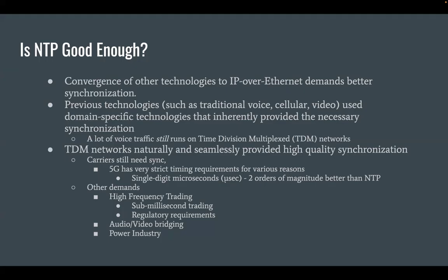As we move certainly from 3G to 4G, but especially 4G to 5G for cellular, we have very strict timing requirements at the radios. The radios need single-digit microseconds, which is 2 orders of magnitude better performance than NTP, compared to what we discussed in the previous slide. That's needed to keep the radios in sync for roaming. So when clients roam from one radio to another, that level of time synchronization is important to provide a good